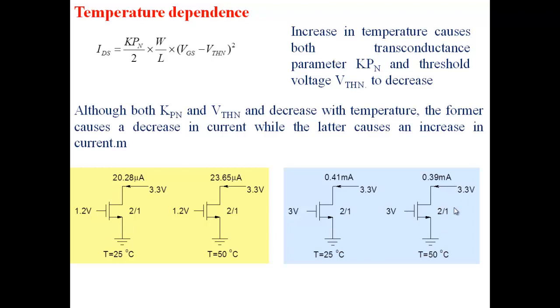And lesser current in general means, as we will see when we analyze, all the speed problem and performance come about because I have to charge and discharge capacitances. When I have less current available and capacitances are the same, since capacitances are more geometrical parameters, dielectrics and all that, I have less current available to charge and discharge the capacitors. So my performance goes down, delay increases and all that.